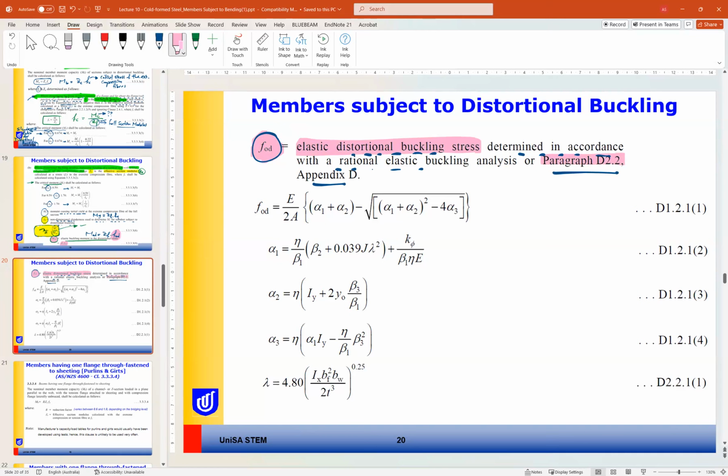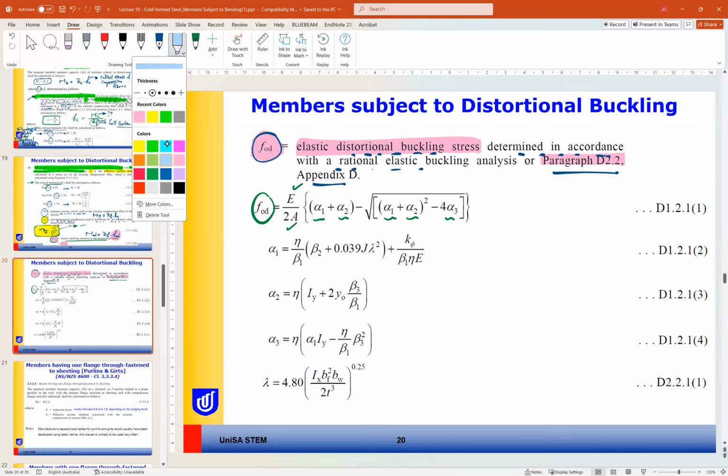Okay, so FOD is equal to E divided by 2A multiplied by alpha 1 plus alpha 2 minus root of alpha 1 plus alpha 2 all squared minus 4 alpha 3. E and A are the Young's modulus and cross-sectional area. So to find FOD, you need alpha 1, alpha 2, and alpha 3. Three parameters.